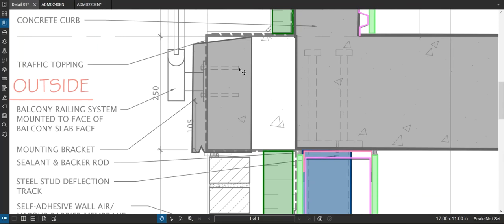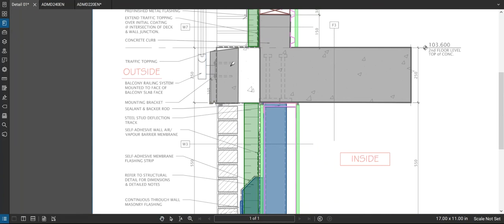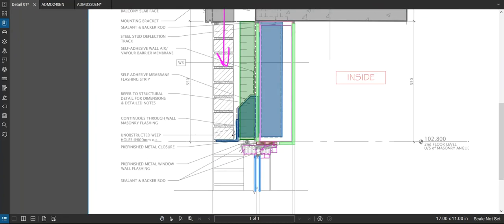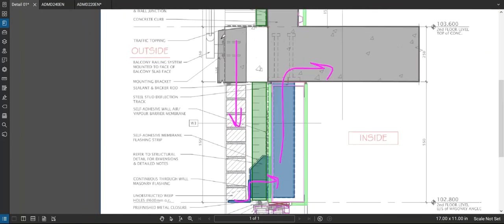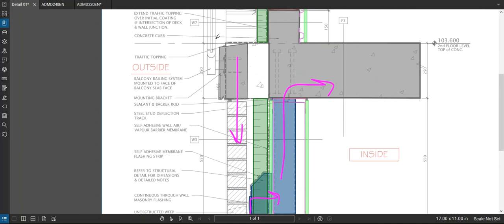Okay, and so it sounds pretty simple to add this, but it creates complications. So you probably wouldn't want to attach the railing to the front of that anymore, because again, this would be axial loaded onto the brick right here like this, and the loads are going through the shelf angle to that steel there, which I guess is transferring it then to the superstructure like so. So it wouldn't be a good idea to put a railing on the outside of that, obviously, because if you pushed on the railing, it'd be pretty easy to start to wiggle that loose. So you'd have to deal with the railing for one thing. I wouldn't even recommend putting the railing on the top of that. I think that's not a good idea.